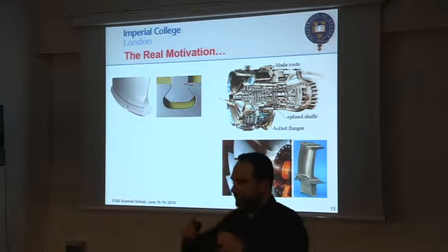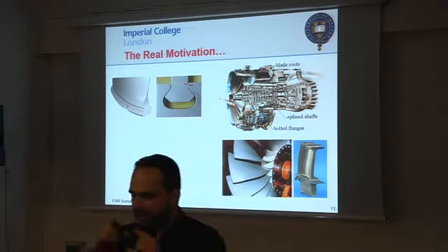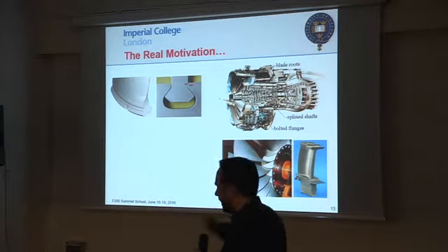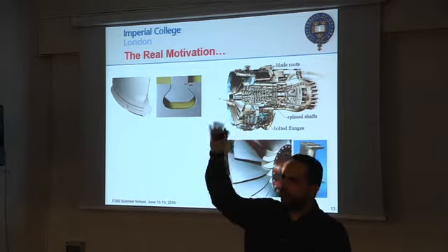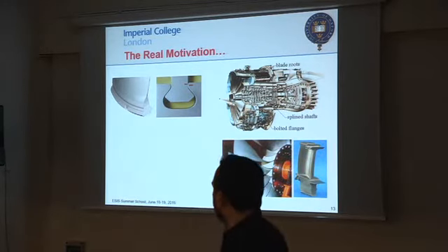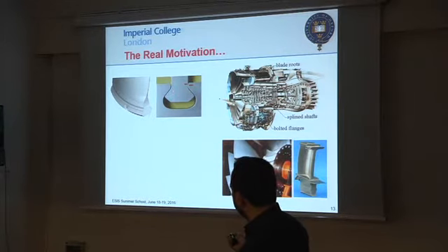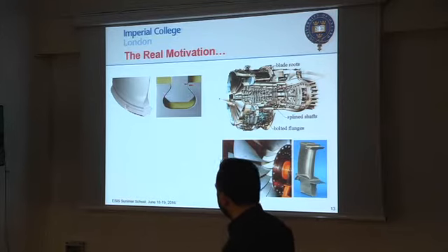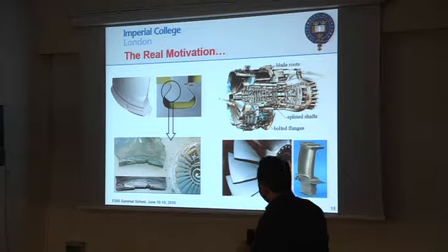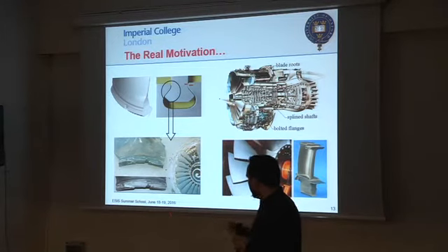So you have a dovetail, and the dovetail is mounted on the disk. And therefore, if you think about after you run it, you apply the load, the blade vibrates, the blade has got centrifugal force. After a while, you might get cracks, and the crack usually starts at the contact between the disk, which is this one, and the blade, which is this one.